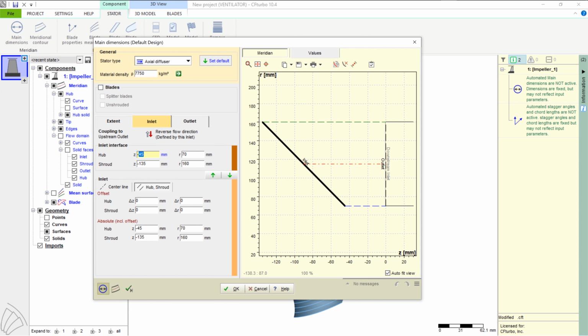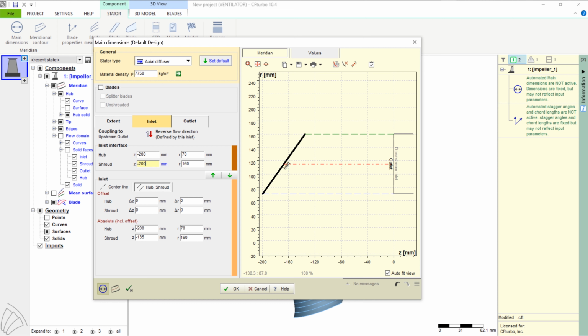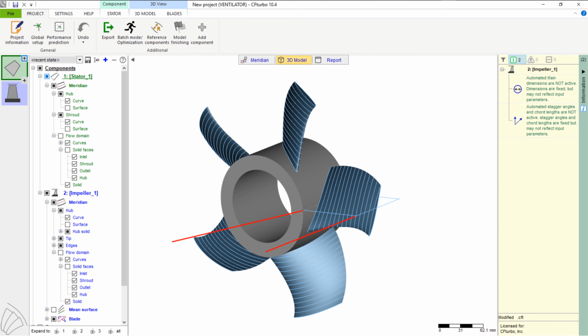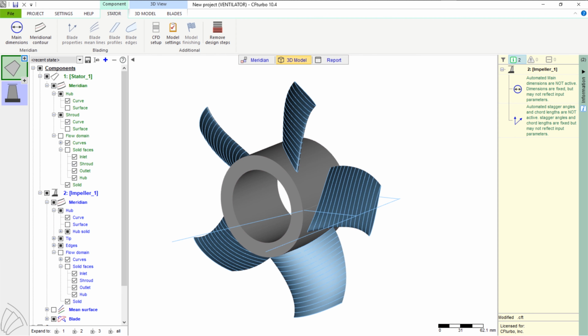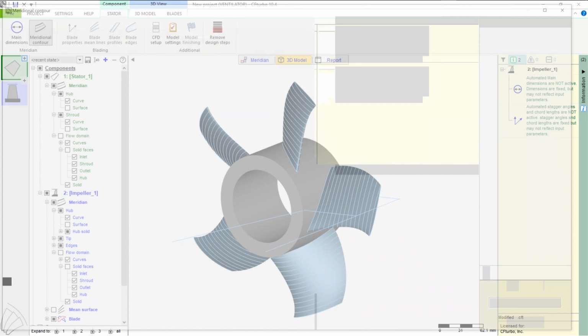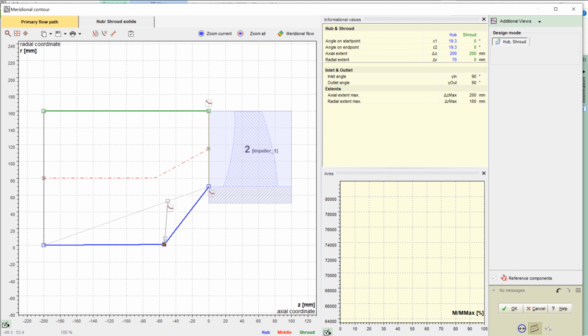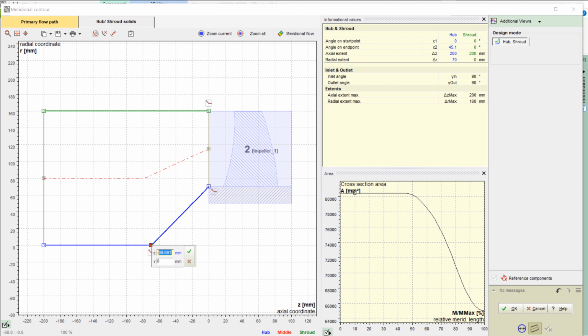To prepare the CFD setup, first we add an inlet extension, including a simplified hub nose. For this purpose, we apply the stator module of CFturbo, which can be used to make vaned and unvaned turbomachinery components like pumps or guide vanes. The inlet pipe should have a certain length in order to prevent an impact from the boundary conditions to the fan stage itself when running a flow simulation.